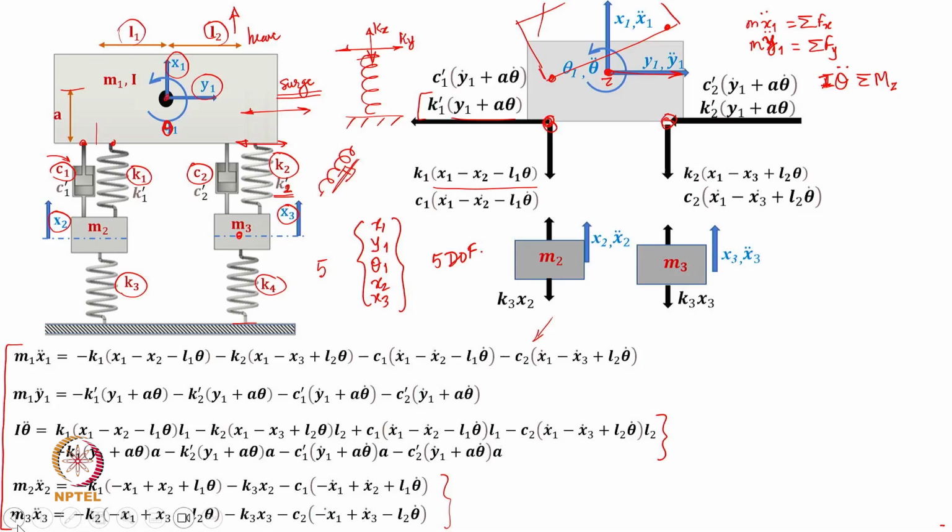Many times it makes sense to use the energy method. So, you define the energies associated with the velocities of the masses. You write kinetic energies and potential energy arising out of the strains in the flexing elements like springs here, and that can lead to similar governing equations of motion. In fact, you are expected to get the same equations by application of Lagrange's equation.